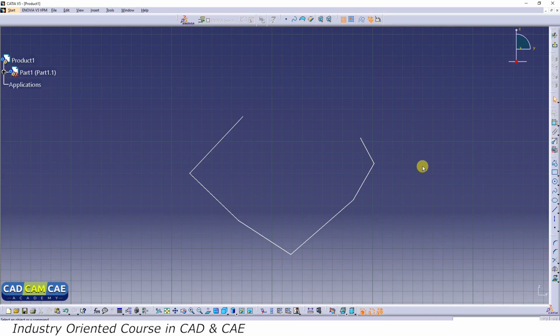If you remember manual editing, you can hold, grab and drag to modify the geometry. So let's try. Here when we are trying to modify any element, the adjacent element is also changing. Let's try this point. The same thing is happening. Let's try this entire edge and you can see the adjacent edges are also changing.